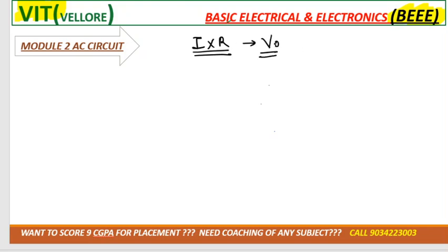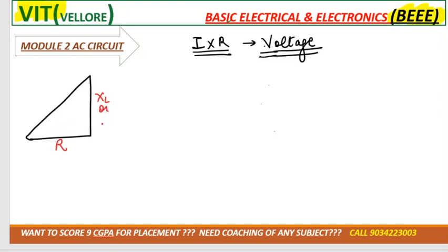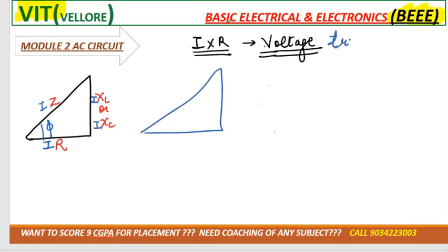It will become voltage, right? According to Ohm's law, V is equal to IR. Now we'll draw the impedance triangle and multiply by current, then we'll get the voltage triangle, right? Like here was R, XL or XC, and Z. So here we can multiply current I into R, I into XL, I into XC, and I into Z, right? So this will become a voltage triangle.